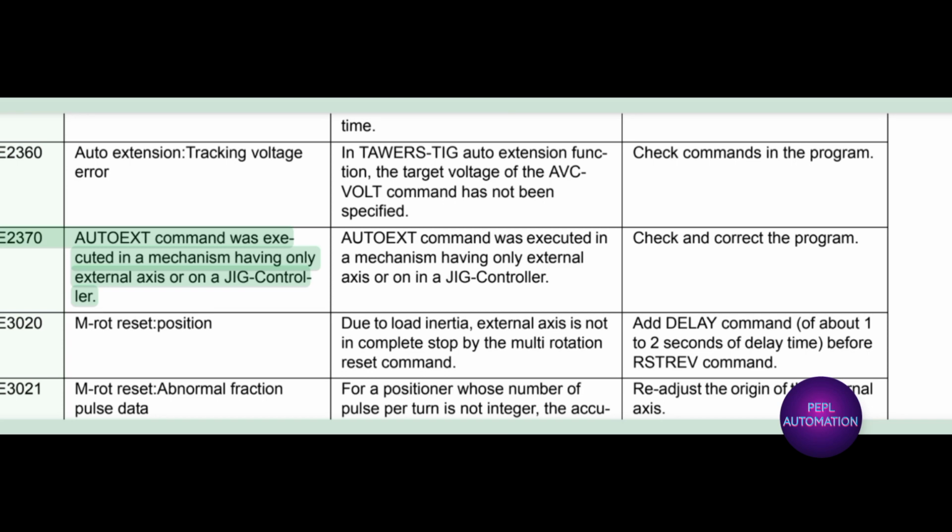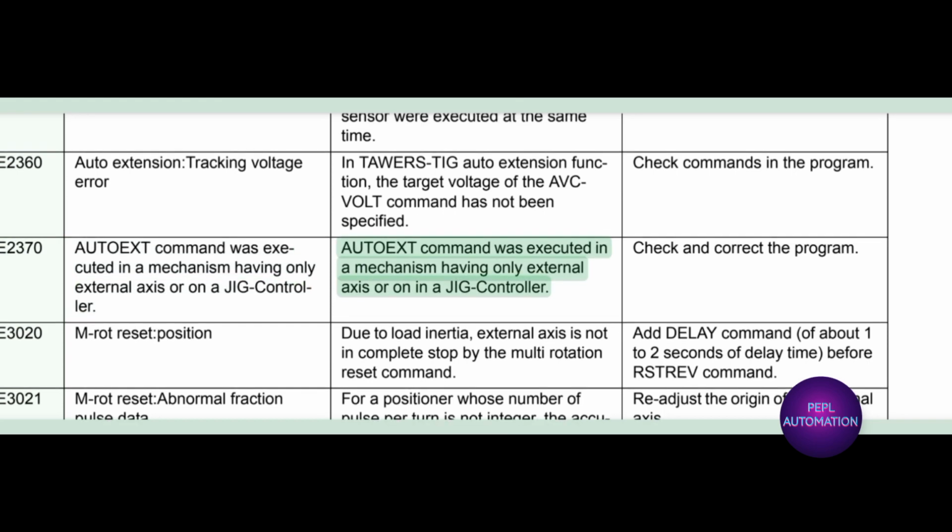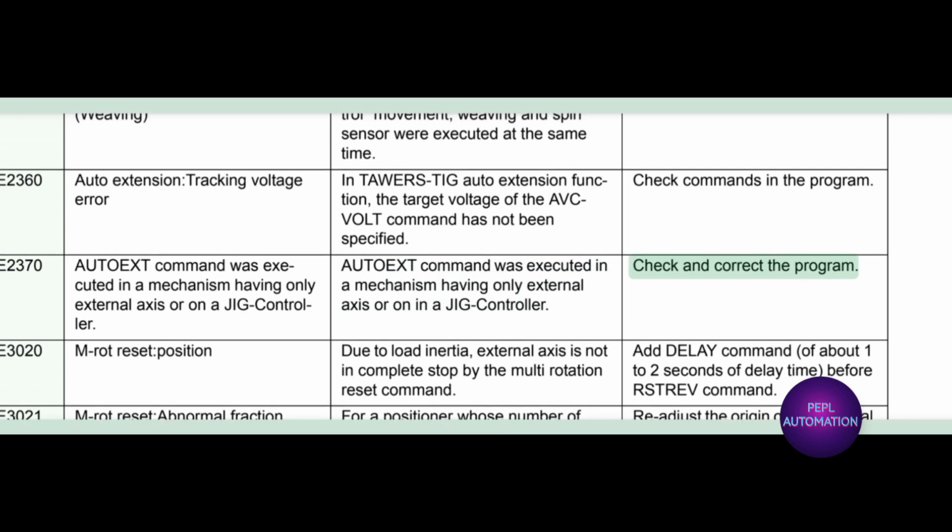E2370 AUTOEXT command was executed in a mechanism having only external axis or on a jig controller. Check and correct the program.